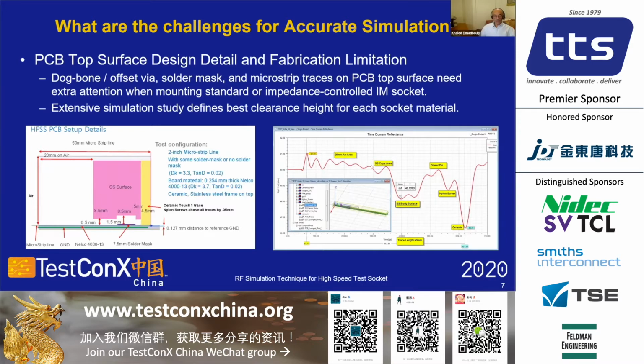And as you can see from this slide, when we analyze the TDR, this is the 50 ohm microstrip trace perfectly exposed in air, and then there is some impedance discontinuity or mismatch when you have the stainless steel above the microstrip trace. The dowel pin is actually recessed a little bit more inside the probe head, so the dowel pin does not affect the microstrip trace because it's a little bit further away.